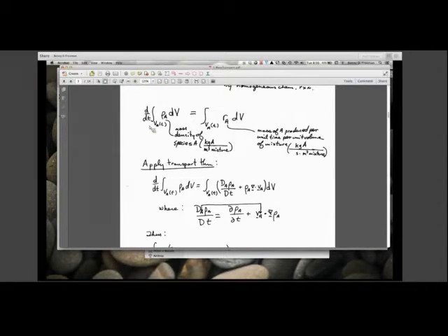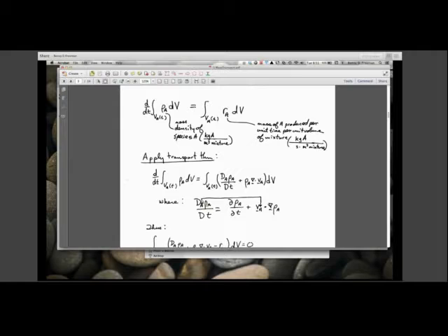Okay, it's simpler than that. It's simply that if I asked you to take out a sheet of paper right now and take the time derivative of this term, it's not just the integral of d rho A dt dV, right? Because the limits of the integral are also functions of time. And you remember that when the limits of an integral are functions of time and you need to differentiate that integral, you need special rules.